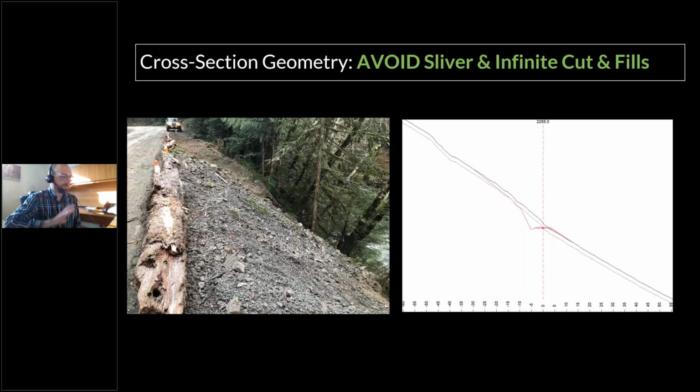Now, this isn't an uncommon problem on steep slopes, and perhaps you can mitigate the problem with stability enhancements. So maybe you build a key and rock fill, for example, or to have a steeper fill slope angle. Perhaps you can develop a plan that uses temporary cuts and fill slopes and an appropriate inspection, maintenance, and decommissioning plan. Oftentimes, a very useful solution, though, is to just move your road. And it could be a minor adjustment, or it could be selecting an entirely different route, depending on what you're up against and what makes the most sense.